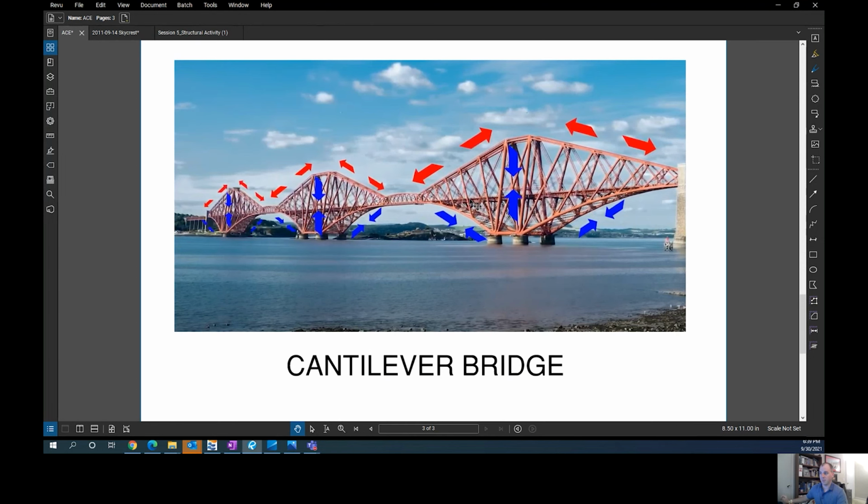The next bridge type we looked at with Nehemiah was the cantilever bridge. In this bridge, all of the compression is carried by the central element of the truss or whatever you're using as your superstructure for the cantilever, and all of the tension is carried in the top chord of those cantilevered elements. These bridges are great for long span conditions, such as seen here, because again, similar to the cable stay bridge, you can build out from each point of fixity. Those fixed points of fixity are the central piers, here and here.